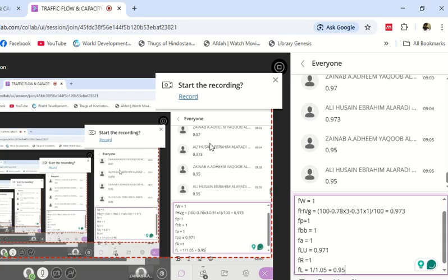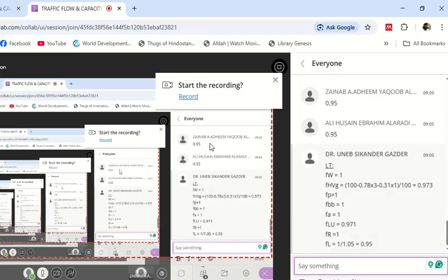Okay, any other factor I can use? Okay, the rest of the factors we are not doing it. Okay, and we don't have swivel back, we don't have lane blockage, nothing is given. So we can keep ourselves to this. My S will be 1900 multiplied by all these factors. 973, 1, I don't need to multiply with 1. It will remain the same. So I'm just multiplying with the factors which can have an effect.